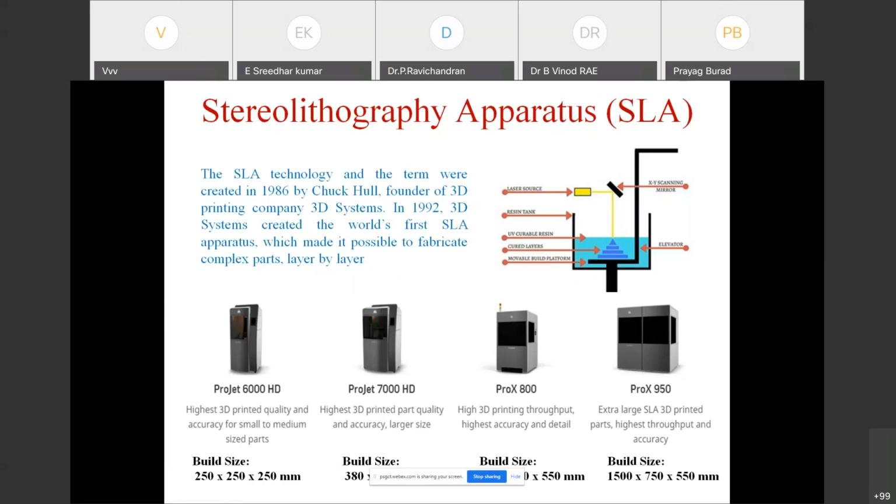Sorry for the difference actually. So in the early stage, while stereolithography was launched, there were options which were largely used for photo model development. In the latter stage, a lot of material development happened for this segment. Now we have materials of different choices according to our functional requirement, maybe having flexibility or high strength or thermal requirement. On that basis, you can opt easily for stereolithography.